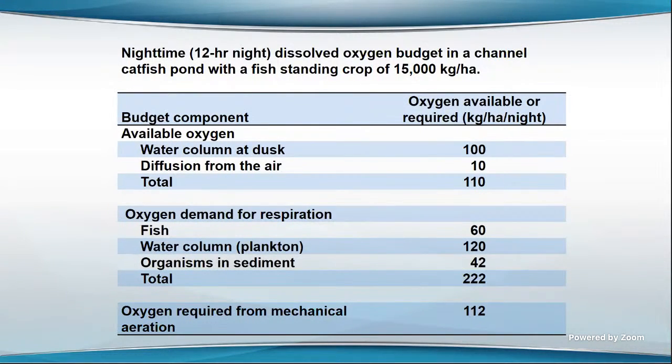Now, I thought when I first figured out you could do that calculation of the BOD on feed, that we could take these wastewater engineering calculations where they know in a wastewater treatment basin how much the waste load is. These things are lined with concrete. They just dump the sewage in there. There might be some sediment at the bottom, but they keep it stirred up pretty good in those systems, so it doesn't accumulate. And so they can calculate how much oxygen is being used per hour. Those things are actually measured. And they can estimate from the performance of the aerator that they've done in tests how many horsepower of aeration they need to supply the amount of oxygen they need per hour.